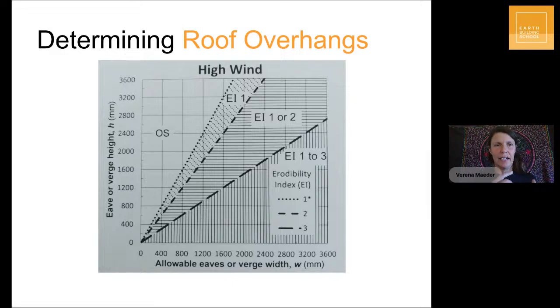And the way that the New Zealand standard looks at the weatherproofing equation is that you take into account the erodibility of your material. I actually have done live streams on this as well, but the actual building material is tested before it goes into the building. And one of those tests is an erodibility test. The results from those tests will give you an erodibility index, this is the EI in this table. So it flows into the equation.